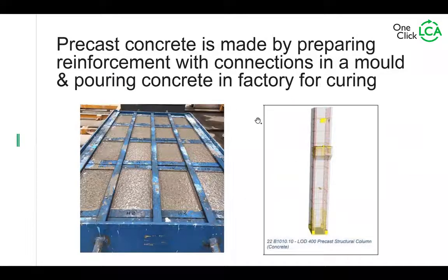So then we have precast concrete. It's the same as ready-mix, actually. The only difference is that the mold is not on the site, it's in a factory. So you pour it there and you let it cure, and then you deliver it to the site. And the precast, of course, has some advantages to it. One of them being winter conditions. If it's winter conditions, it's much easier to manage the curing in a factory. And there's also the possibility to sometimes optimize strength development time.